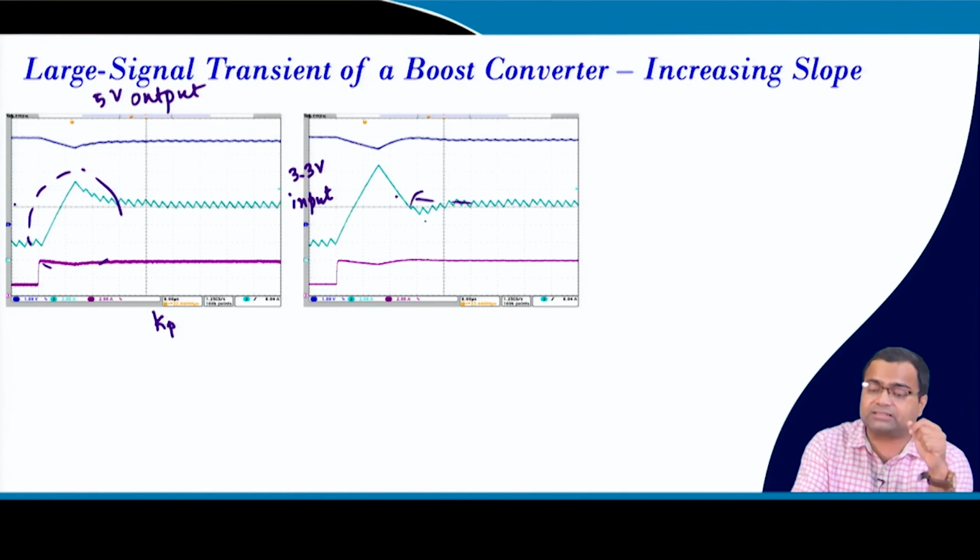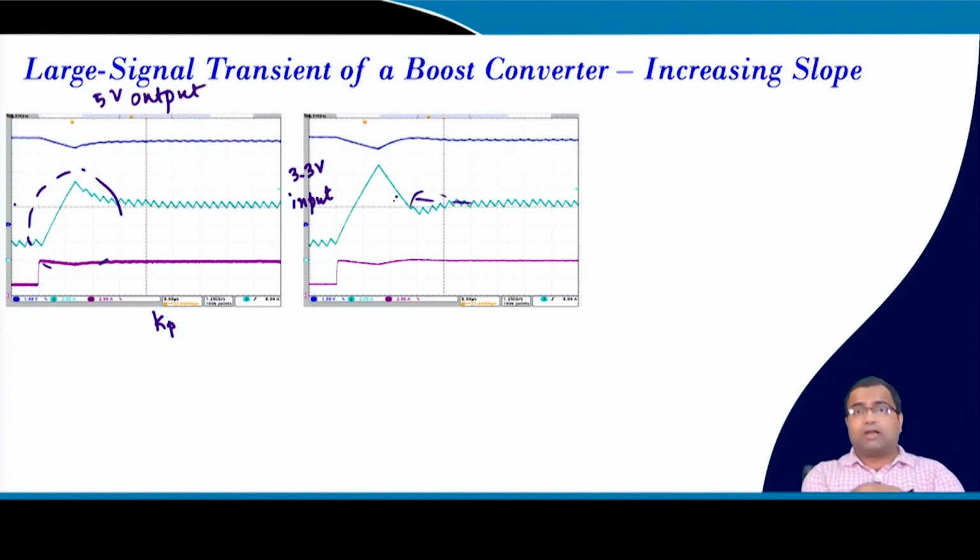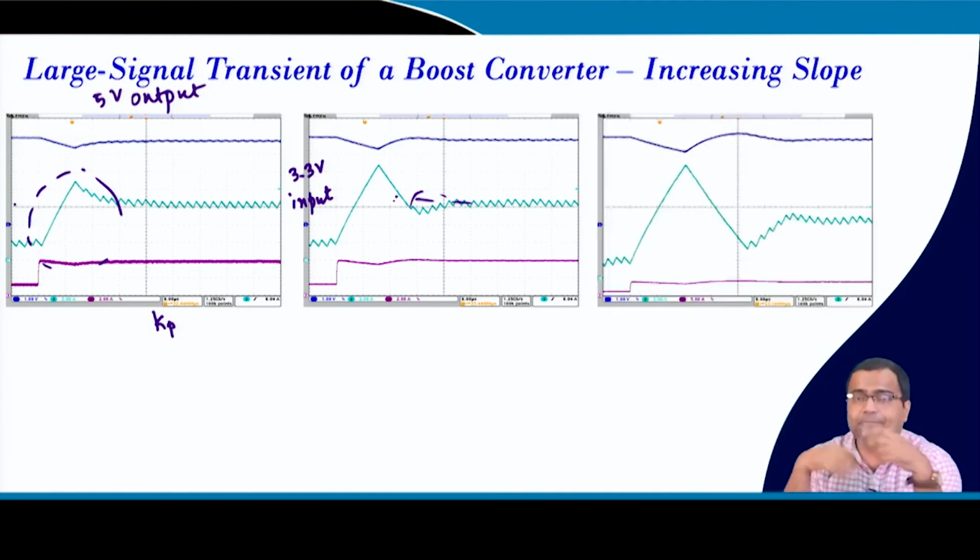This mismatch is coming because we have a PWM modulator, where the PWM modulator itself has a constant. So, we cannot achieve perfect time optimal, we will get rather approximate time optimal, because the modulator will put a constant in the on-off time, right. If you further increase the gain, then you will see the overshoot will increase significantly, and that we have discussed in the phase plane.